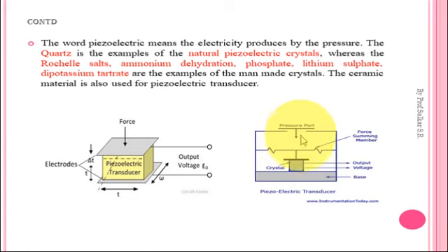Whatever force is coming from this pressure port, these summing members will move in an up or down direction according to the quantity of force. Whatever quantity of force is applied, according to that these force summing members are flexible to move to the upper side or lower side, or they can move right or left. As they move, they apply the same amount of pressure to this crystal. The crystal is connected directly to the force summing member. So when pressure comes from this pressure port, it goes on to the force summing member, and the force summing member gives that particular amount of pressure to the crystal.